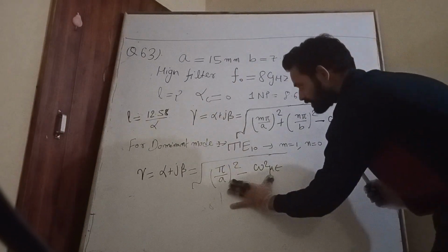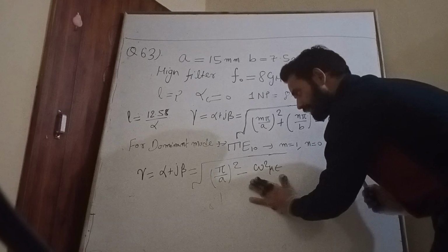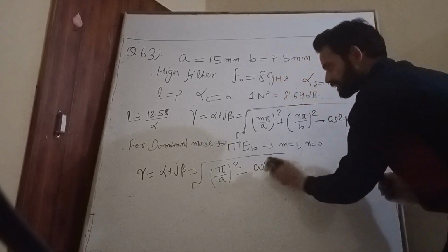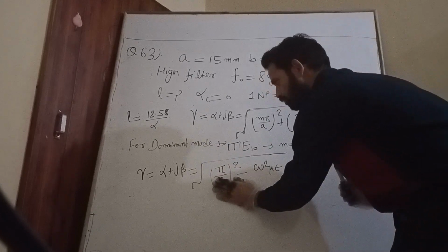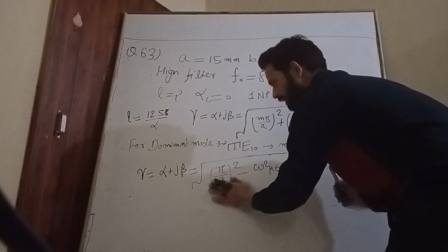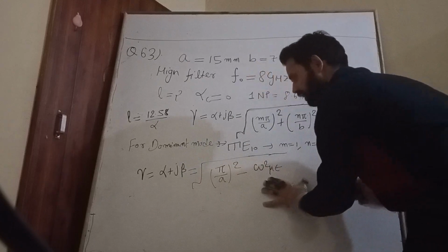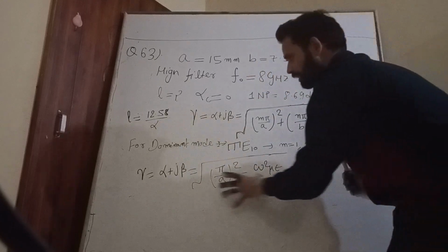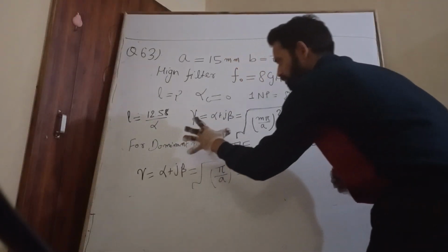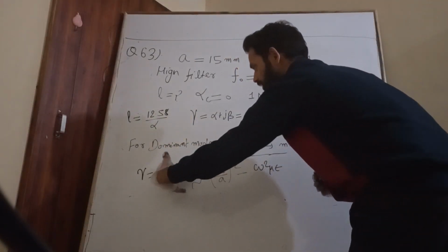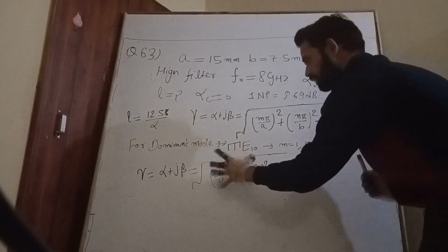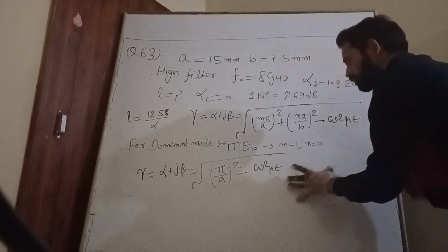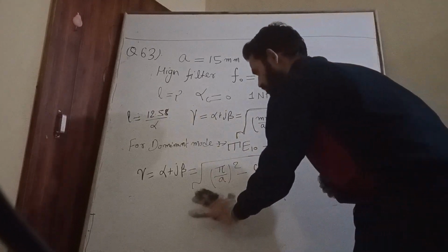Now if this factor comes negative, less than 0, then it is under a square root. Any negative value under a square root is imaginary. Imaginary means that the wave propagating through the waveguide will completely propagate through the waveguide, and there is no attenuation at all.